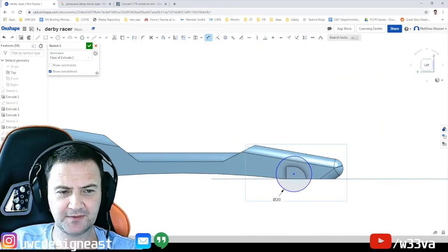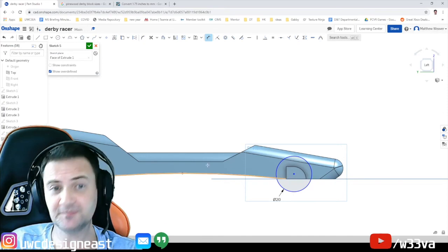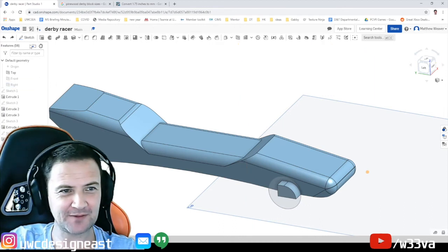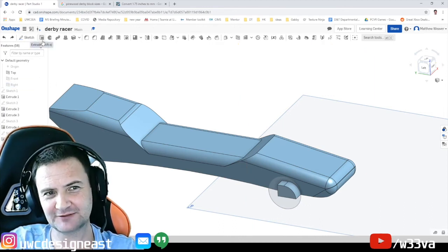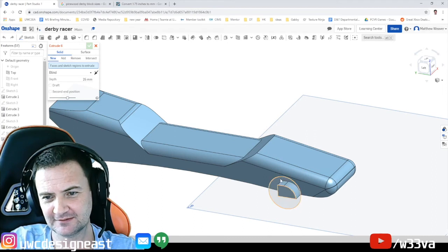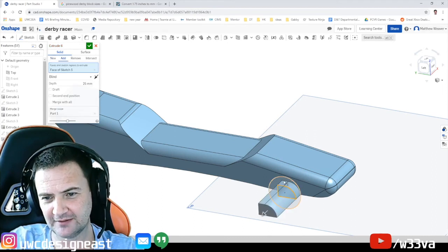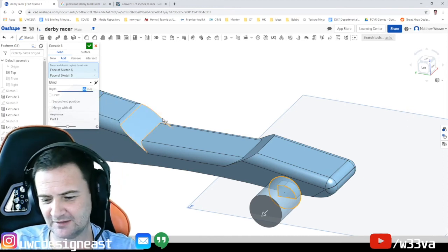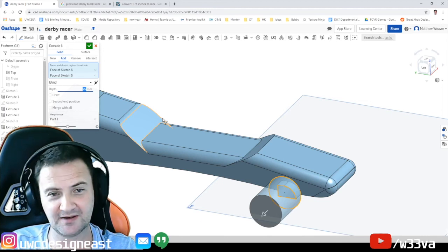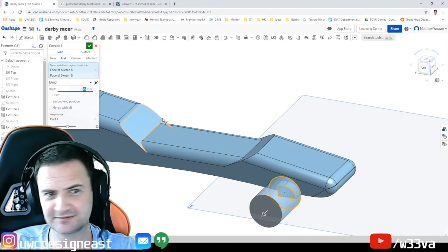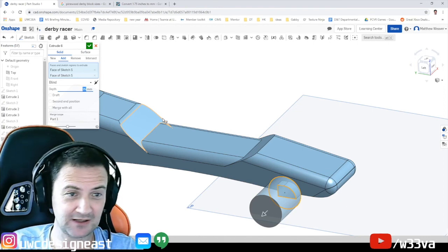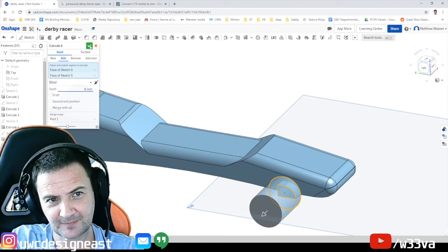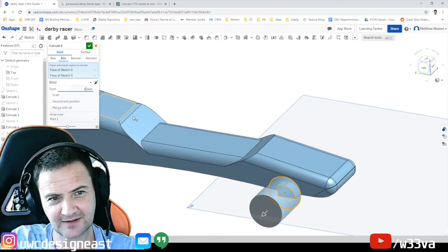Now I can either copy the sketch and extrude it 4 times, but easier to extrude it now so that I can just copy that part. This sometimes gets a little bit tricky because if I extrude it, that's the sketch. We are going to make our own wheels from laser cut acrylic or MDF. If you can get the acrylics, are much faster. But don't tell anyone I told you that. And I think we use 6mm acrylic. Now, so that's a depth of 6mm.